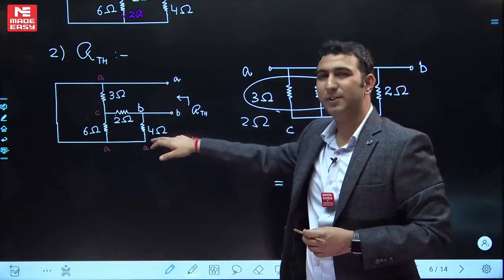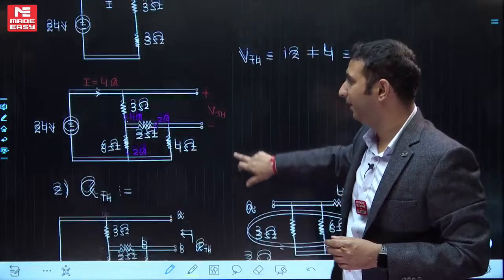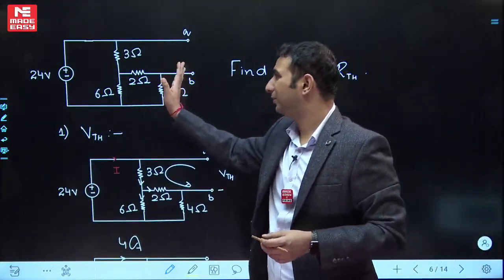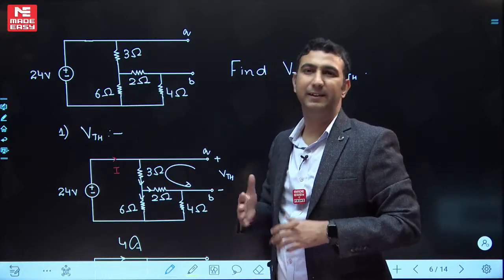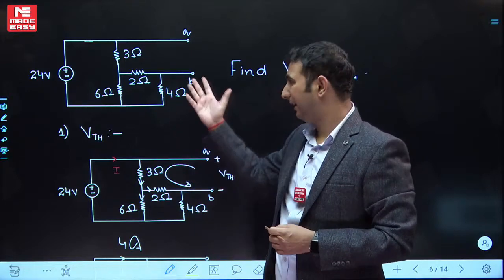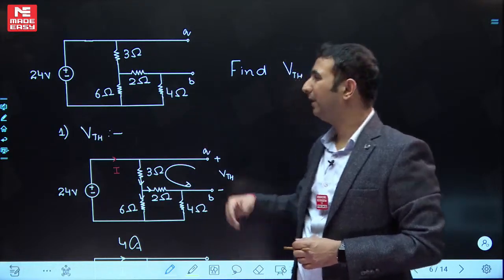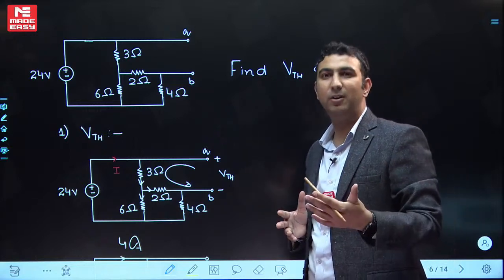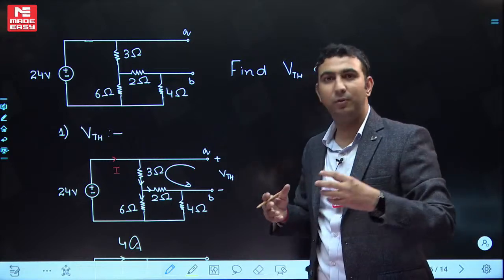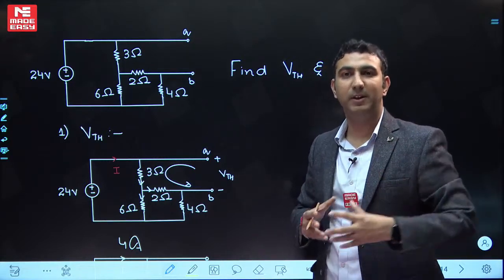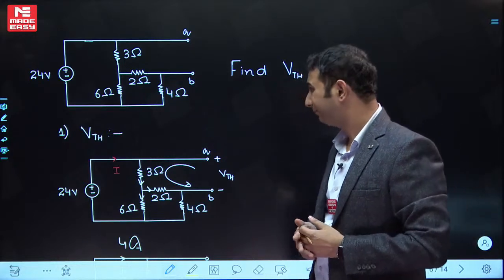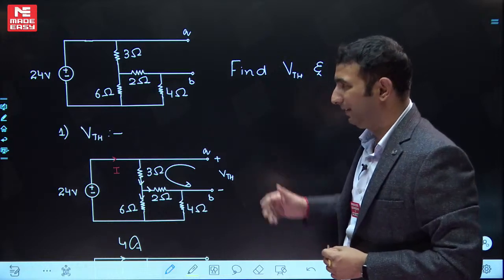So remember the equivalent resistance concept. You already know these things, studied in the class in great detail. And this is a different thing because point B was going to get eliminated for calculating I and then current division back. If you want to go with another method also, you can, but I think the current division method is the easiest one in this question, and it's a good concept. You need not always go for nodal and mesh. Whenever you see a question, you do not think about KCL or KVL or current division or some other method; you straightforward go with nodal. That's what you do most of the time. Please do not do that. You can think about something else also, like in this question.